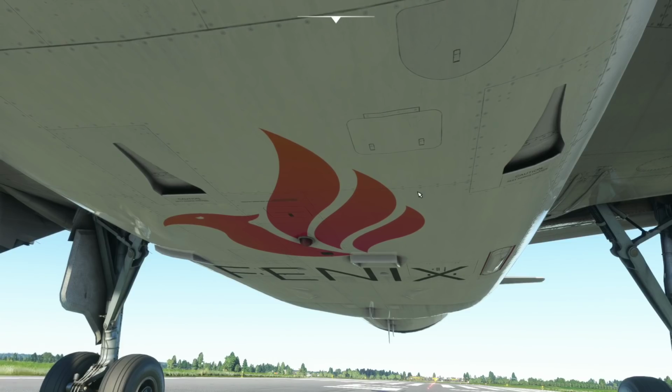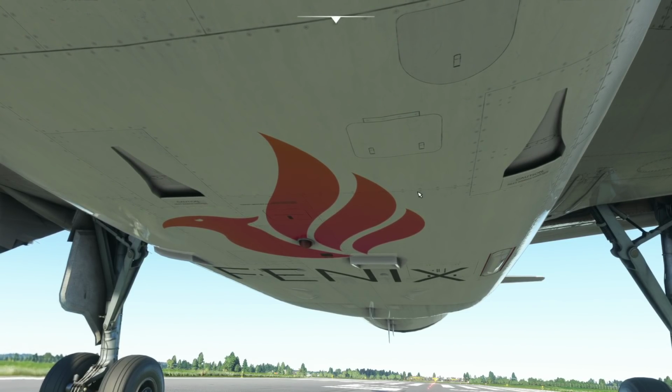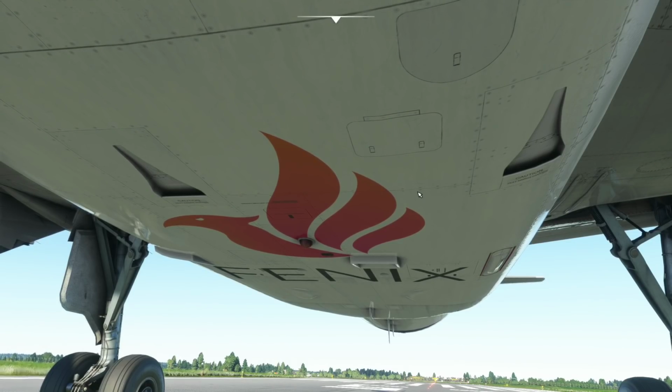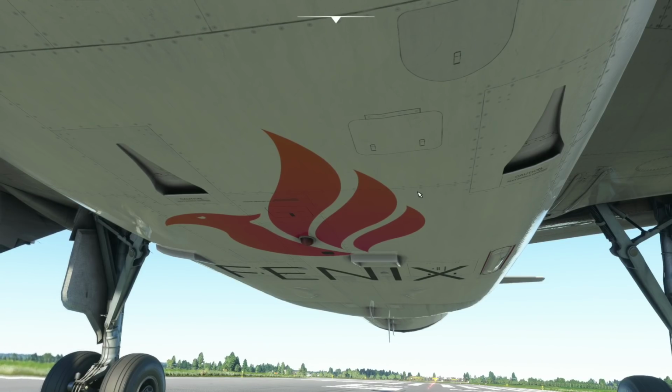So if I just ram it into TOGA power, there you can see the flaps just closed ever so slightly. And if I bring it back out again, you should see them start to slowly open up again. This is again assuming that the airplane has now taken flight. Of course it's a combination of things like the weight on wheels, so the LGCIUs, and the TOGA power and whatnot, for the airplane to basically use its brain and think about whether or not it's on the runway and it needs to close these flaps.